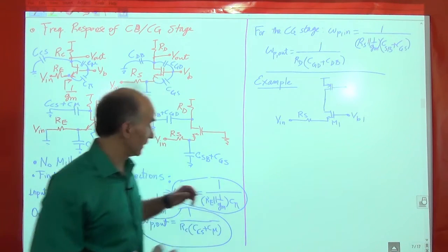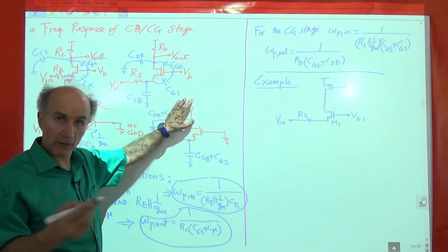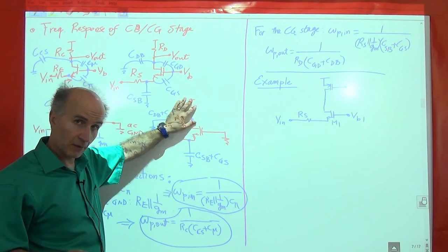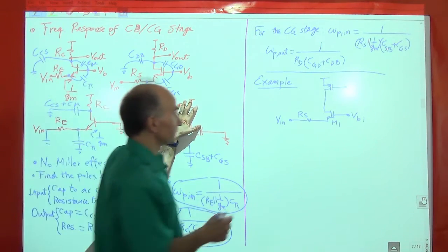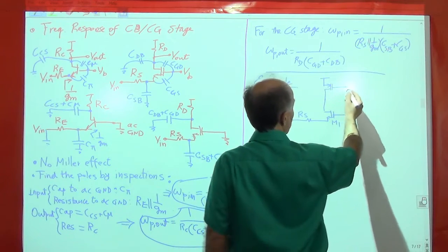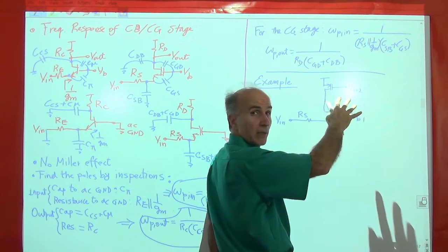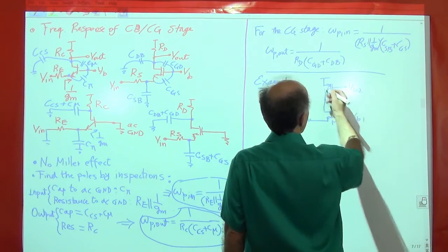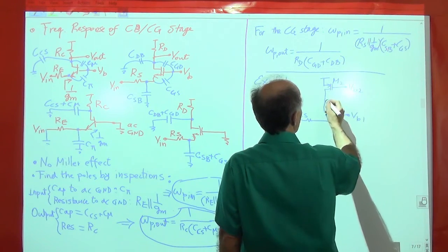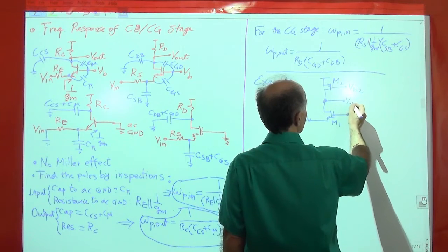And instead of the resistor here, I would like to have a higher gain maybe. So I'm replacing the resistor with a current source. Okay, so here's a current source. This is properly biased by a current mirror here, right? And now we can call this M2, and this is the output node.